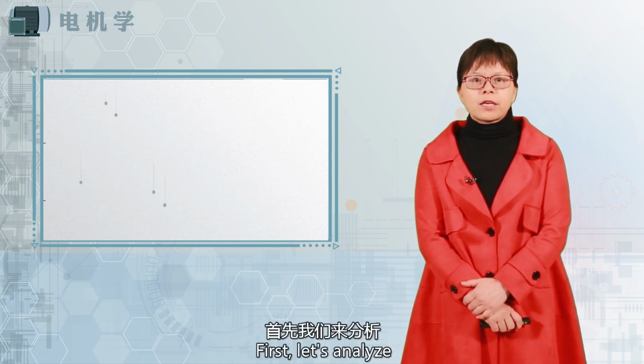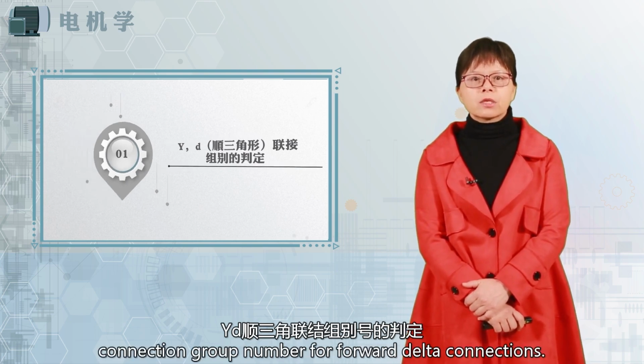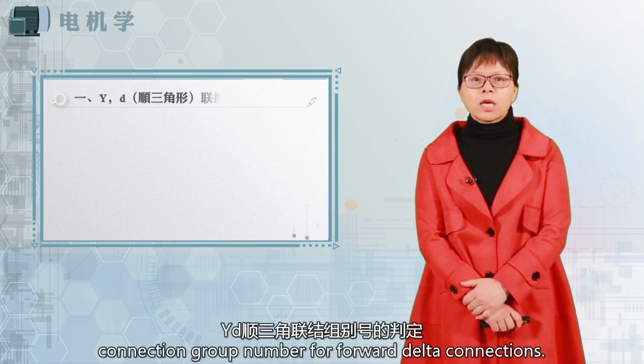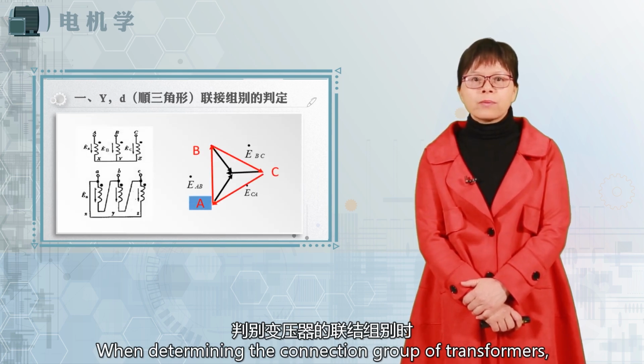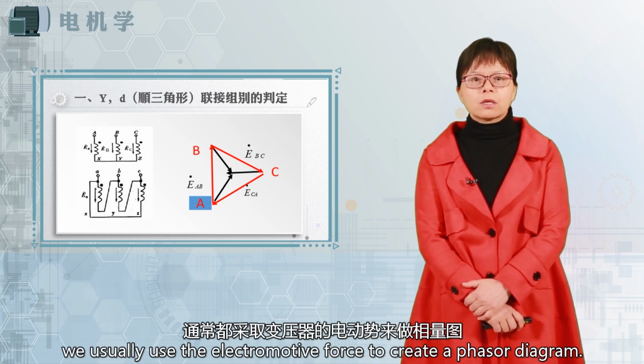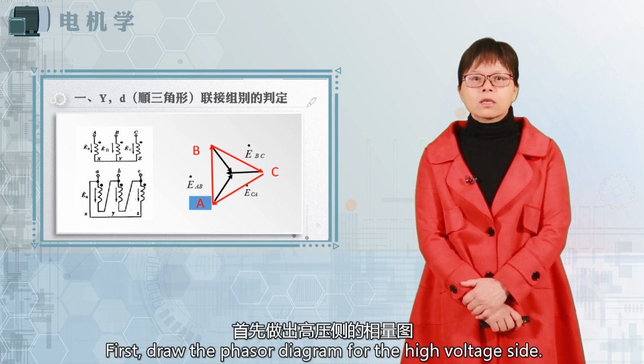First, let's analyze the determination of the YD connection group number for forward delta connections. When determining the connection group of transformers, we usually use electromotive force to create a phasor diagram. First, draw the phasor diagram for the high voltage side.